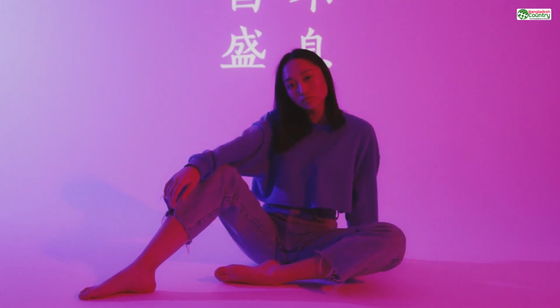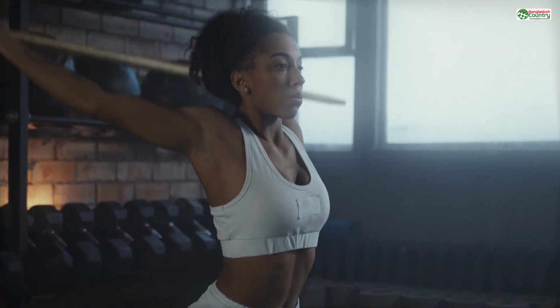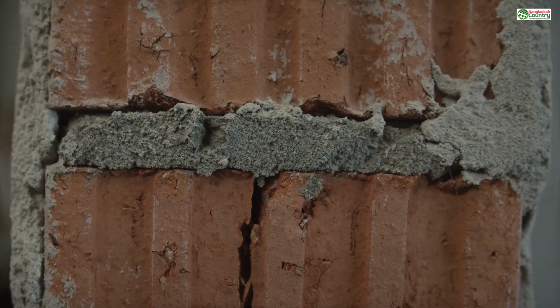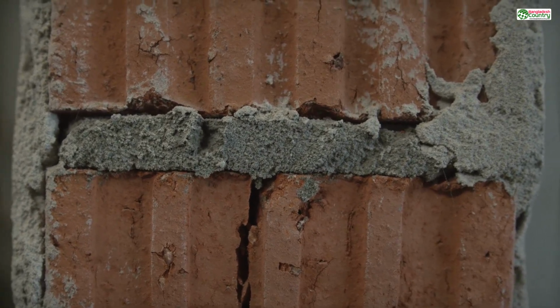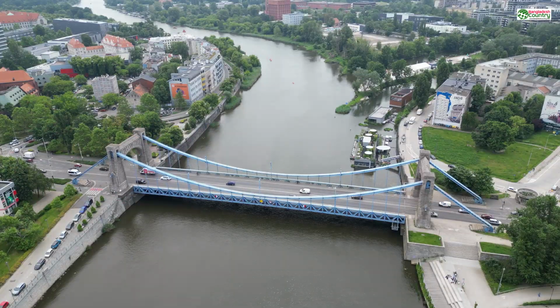First, a general rule of thumb. For most strong, functional parts printed in common plastics like nylon or PLA, a wall thickness of 1 to 2 millimeters is a fantastic, safe starting point. That's about the thickness of a US quarter. If you design most of your model with walls at least this thick, you'll avoid the most common failures.